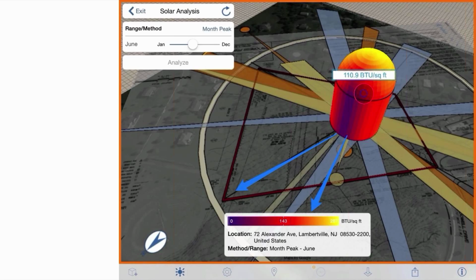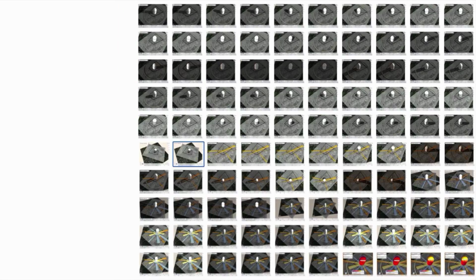Starting to do the solar analysis right within FormIt to understand different times of the day, a curved facade is ideal for that, which is why I do the solar dome on the cylinder. You can understand the orientation, optimize that, understand where your ambient zones are over the course of the day, and try to dial into the location of the building.